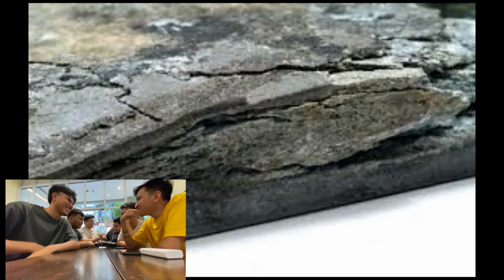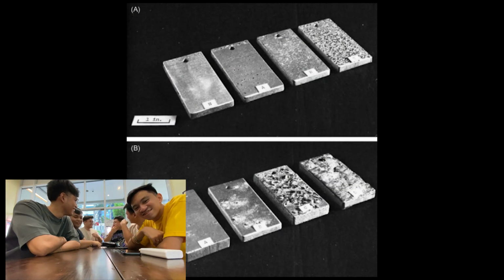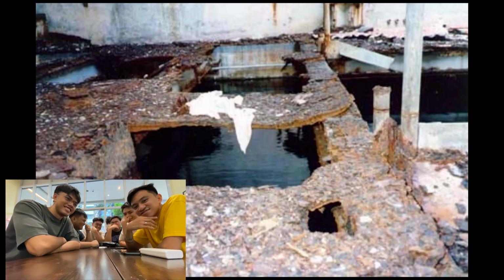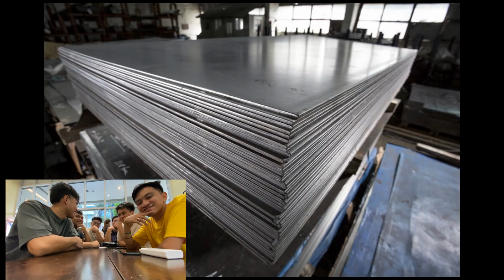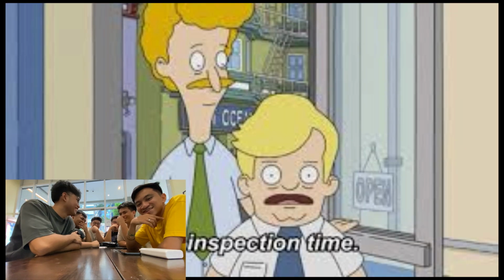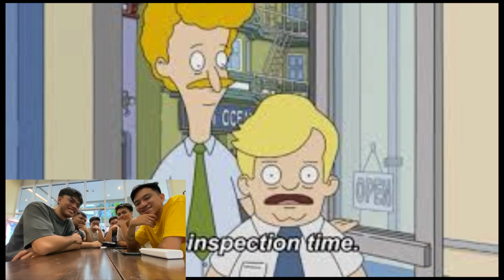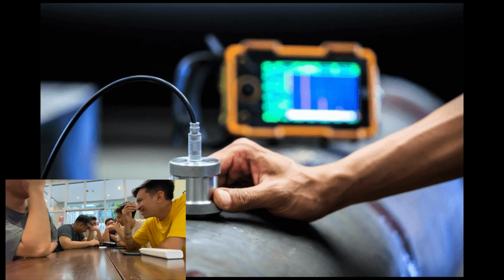3. Exfoliation corrosion. Exfoliation corrosion is a severe form of intergranular corrosion, where layers of the metal peel away. Causes. This type is often found in rolled products like sheets or extrusions, and is caused by the expansion of corrosion products along grain boundaries. Detection. It's usually detected through visual inspection for flaking or delamination, often confirmed by ultrasonic testing.